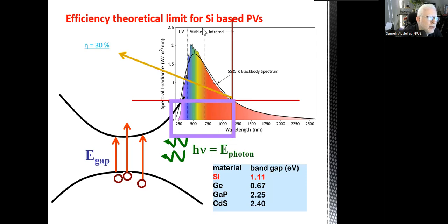Let's use again the laser pointer. So this portion is the only available absorbed portion. Silicon is not capable of absorbing relatively high infrared photons. This is the first limit. But also, please take care that you also have another limitation here, another horizontal limitation.